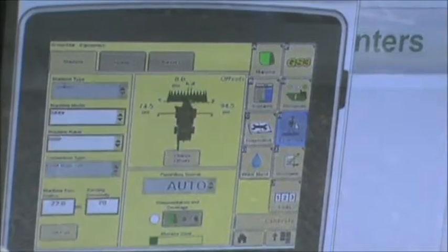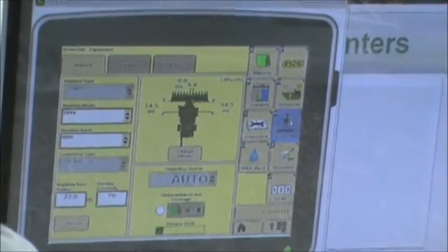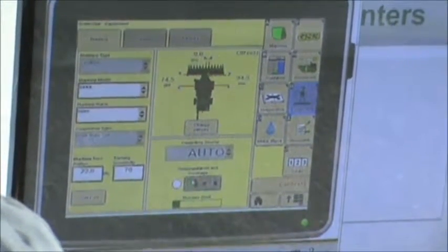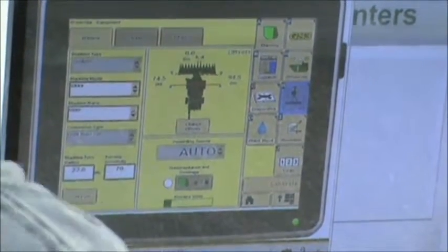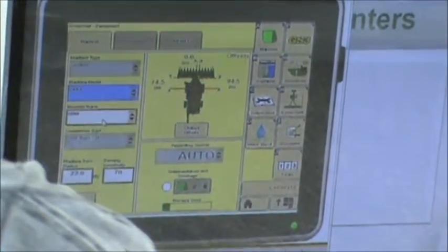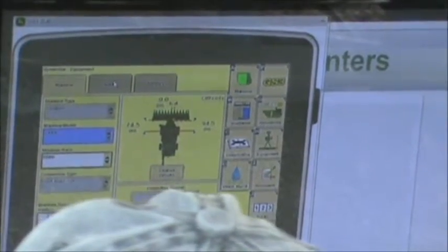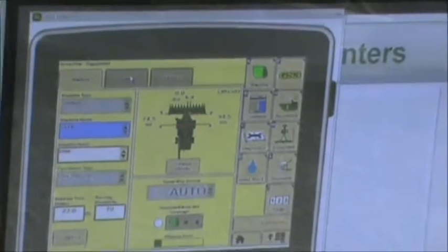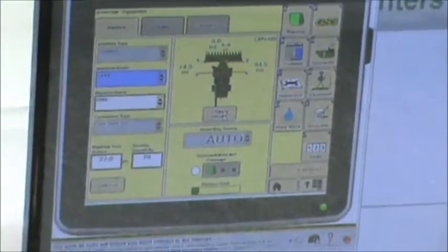Next, we're going to go to our H tab, and this is where we're going to tell our machine what it is and the measurements for it. As you can see here, with the newer combines, this will pre-populate because it communicates back with the display. We've got machine model. This is where you can set what machine model you're using and then the machine number, as well as naming it. On your newer machines, your S-Series combines, they should pre-populate that when you hook things up. It should automatically pop up in there. But you'll still have to give it a personal name, whatever you want to call it.